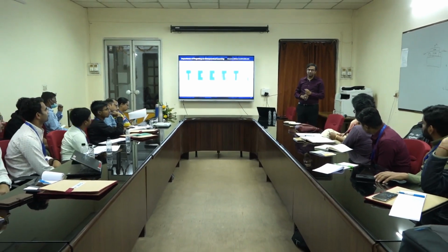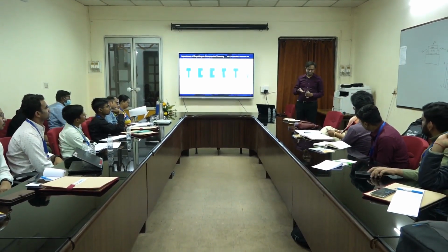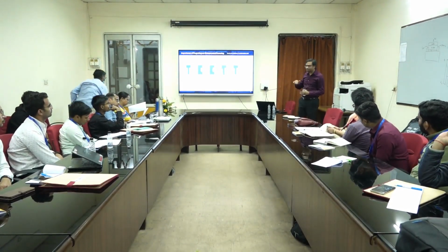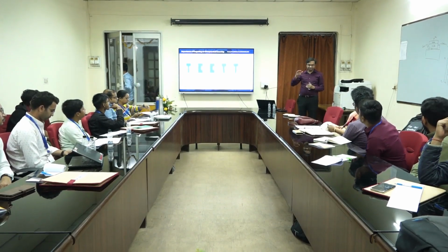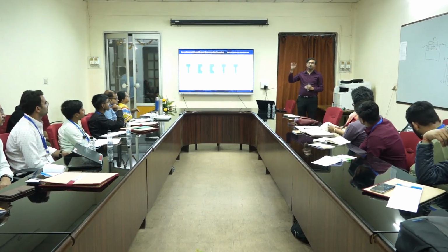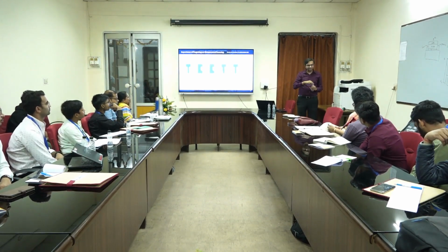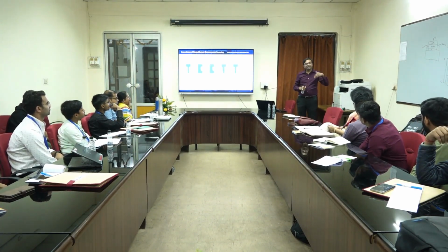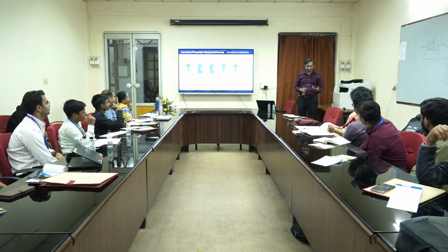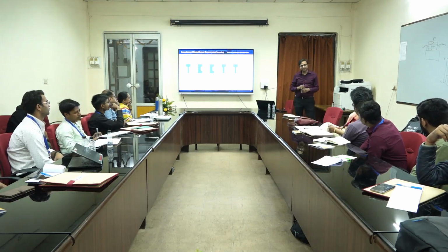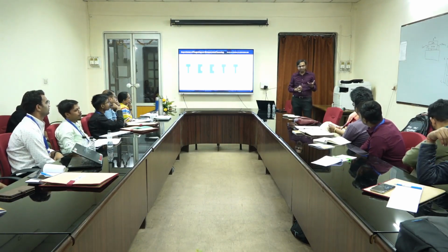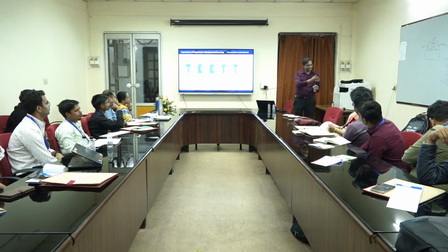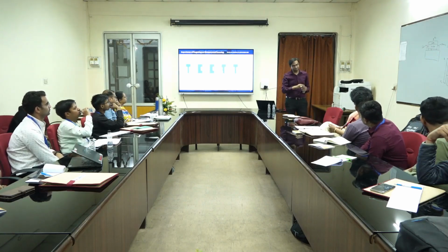So ideally, the intensity of light will impact how fast you learn. If the light intensity is high, you will learn fast. It will go to a state, and then it will be non-volatile, because you're storing the charges, unless you intentionally remove them by applying an electrical voltage. Otherwise, they will decay, but very gradually, and these times are all engineerable by engineering the material stack.